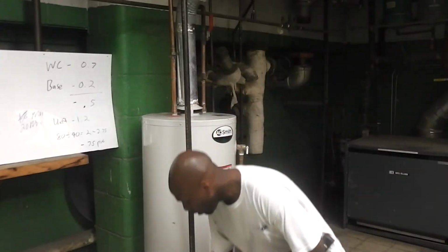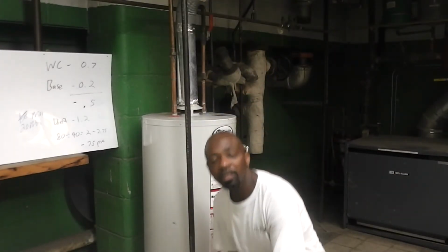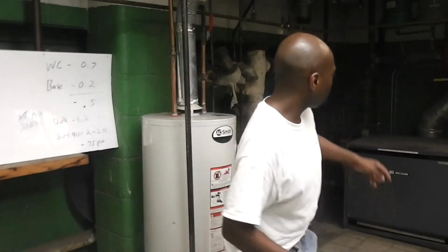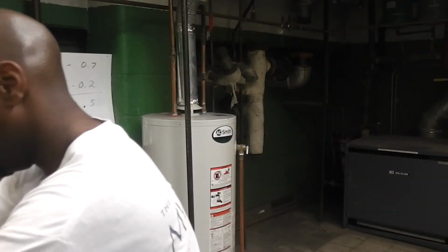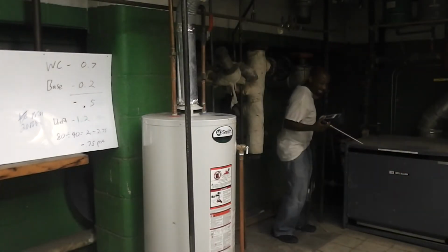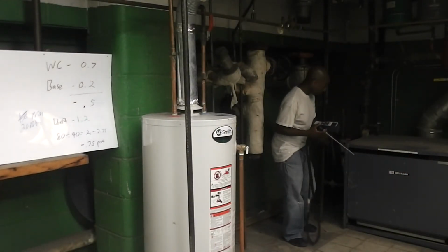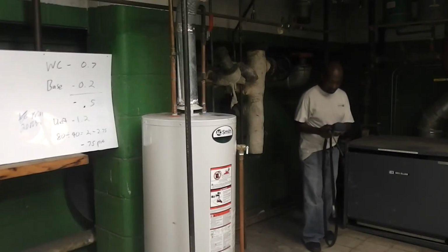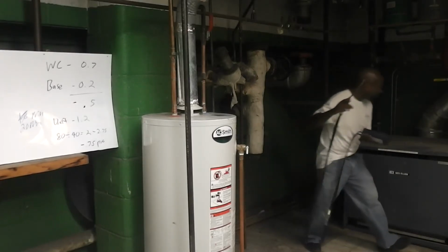So the undiluted CO, I'm going to take my combustion analyzer and I'm going to test literally inside the combustion appliance. So the same setup, check it out. Black pipe, I know automatically this thing is natural gas. So I'm going to select natural gas. Oh yes, right, so we're good to go.